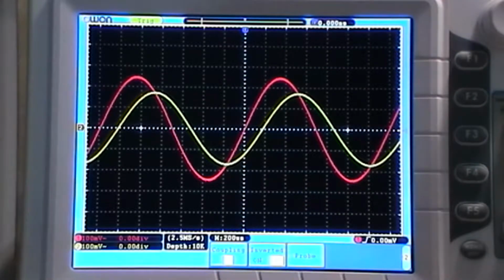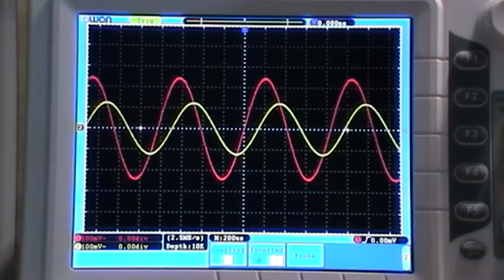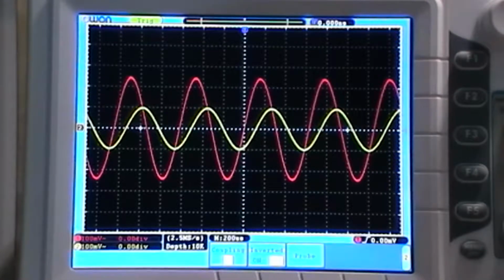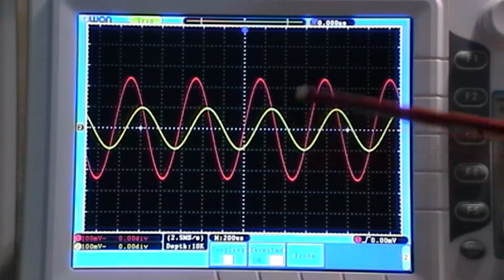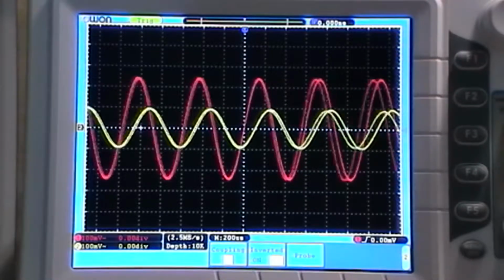I know it looks sort of like it was when I used the 100 nanofarad. So without sitting here and doing all the dB calculations, I wouldn't really know, but I know it seems to be attenuating, and I take it that as I turn this up, it's going to seriously attenuate it even more. 1.6 is where the 100 nanofarad was supposedly starting to attenuate it, and as you can see on the scope now, it's being attenuated a lot more. There's a lot less signal coming through.